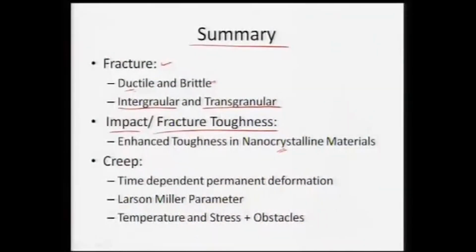Also, there can be 3 different modes: opening mode, sliding mode, or shearing mode. For fracture toughness in a plane strain condition, that becomes a minimum value of the fracture toughness, and that is independent of the thickness of the material, because once we have a very thin material, fracture toughness can start depending on the thickness. To avoid that, we can induce plane strain conditions, and there we can see that nanocrystalline materials will have much more fracture toughness in comparison to micro grain structured materials.